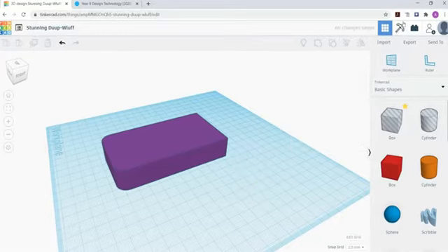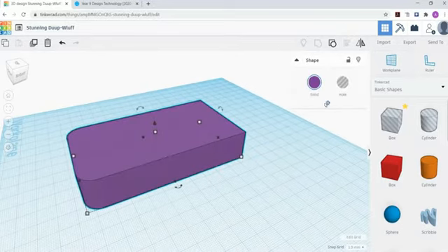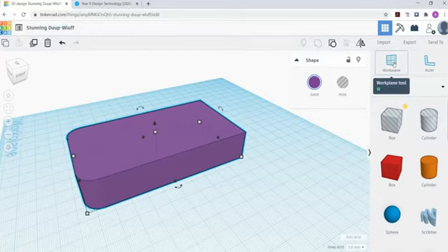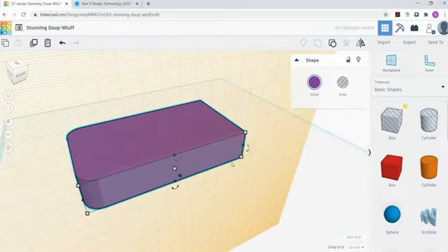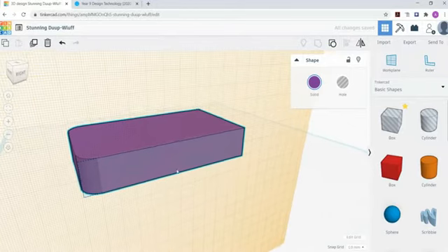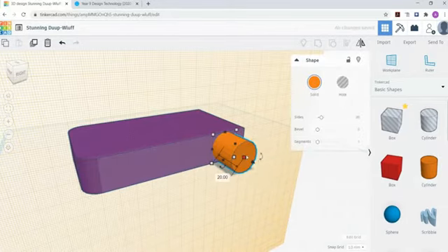But another method that we can do, we can make a work plane on it. So here's what happened. When you drag the work plane and place it on the surface over here, you will have a new work plane. When I drag the cylinder, see, instead of these particular surfaces resting on the blue work plane, now it's resting on the orange work plane.